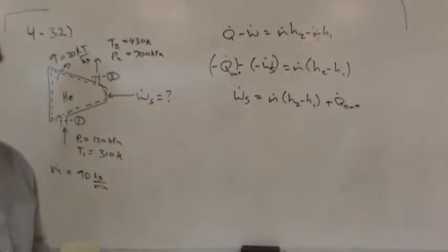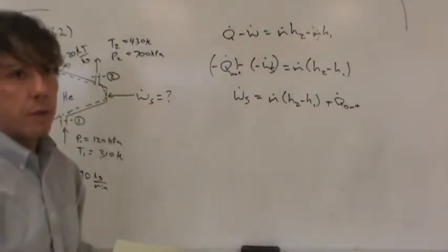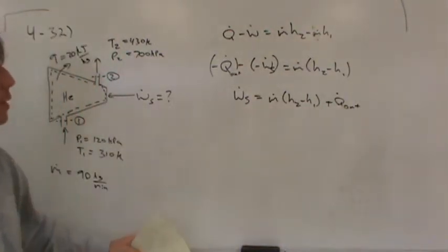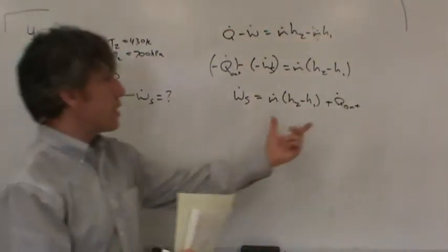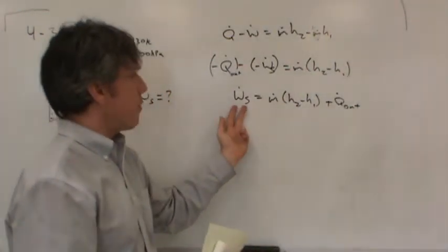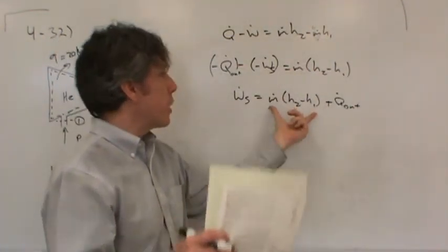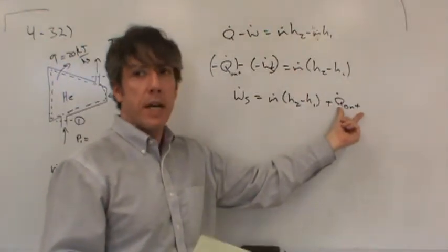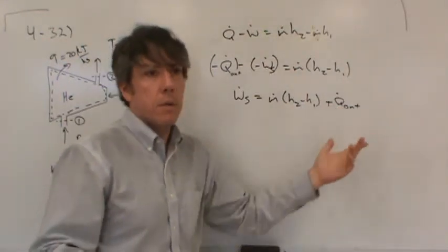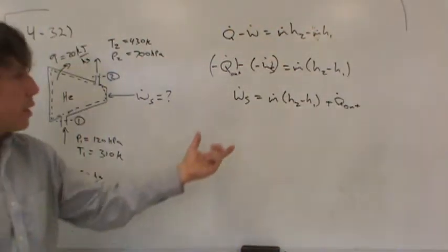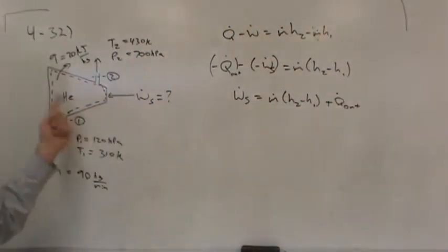Make sense? The sign can be really confusing. That's why I went through this with you. Hopefully it makes more sense now. Now, this actually makes a lot of sense. It says that the shaft power has to provide the energy change of the helium as it flows through the compressor and has to provide the heat loss. And that's what we already discussed and said. So the energy balance actually matches with what our intuition says has to happen here.